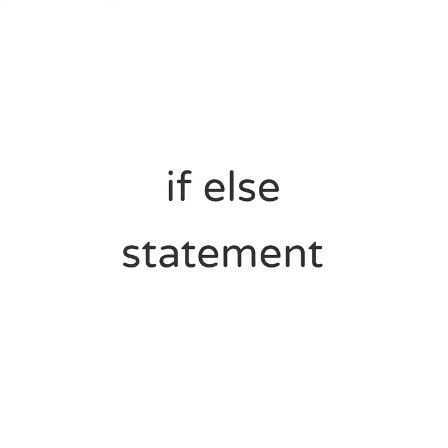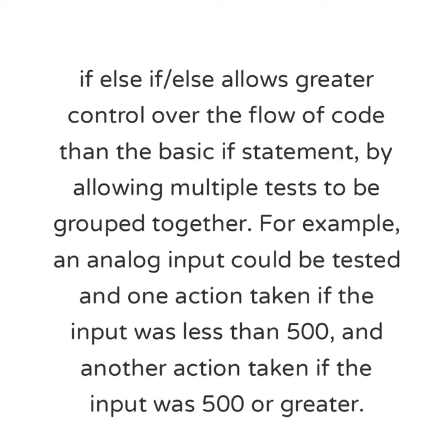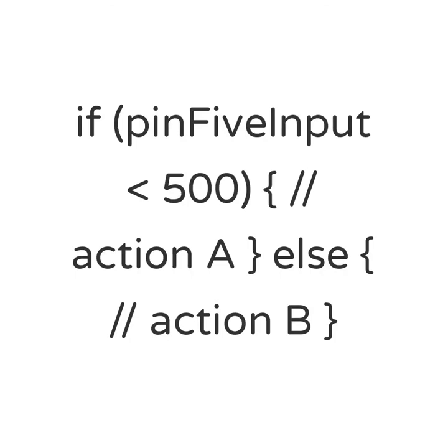The next statement is the if-else statement. If-else allows greater control over the flow of code than the basic if statement, by allowing multiple tests to be grouped together. For example, an analog input could be tested and one action taken if the input was less than 500, and another action taken if the input was 500 or greater. The code would look like this.